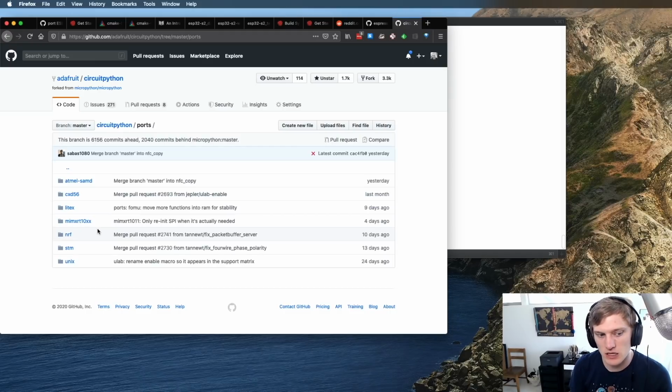Then the question is what goes in it, and how do we hook it into ESP IDF? Because we definitely want to use the ESP IDF, and the reason that we want to use it is because the ESPs do networking, and networking is complicated. Networking and security is complicated, so we'd love to. We intend on hooking up directly to the IDF so that as they iterate, as they fix things, we just inherit it and we update the IDF. So that's why I'm like, okay, we can't really use make. Like we could use, so two options. We use our existing make system.